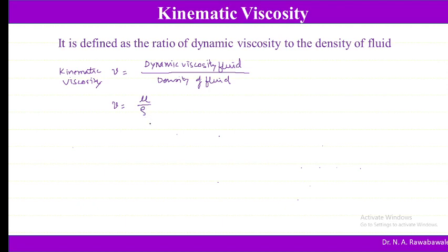The unit of nu: for this mu we had the unit as force into time divided by length square, into 1 divided by density, which is nothing but mass divided by length cube.